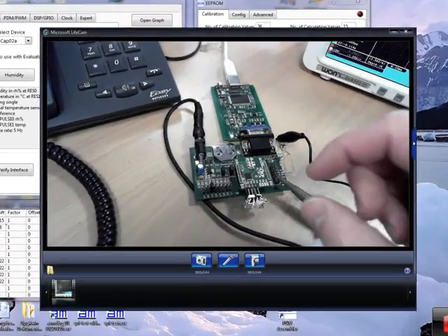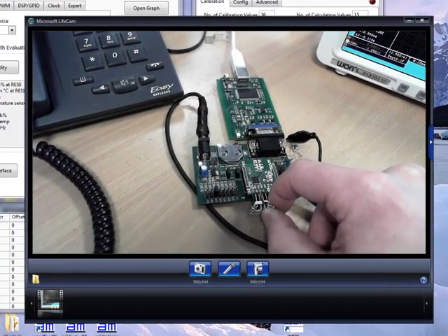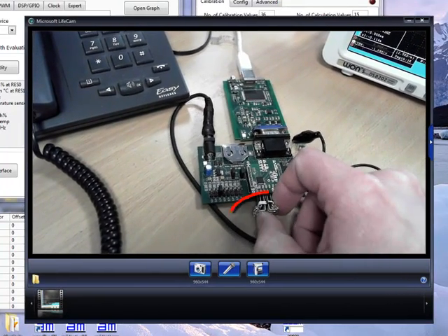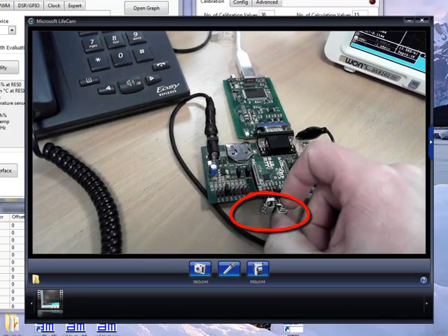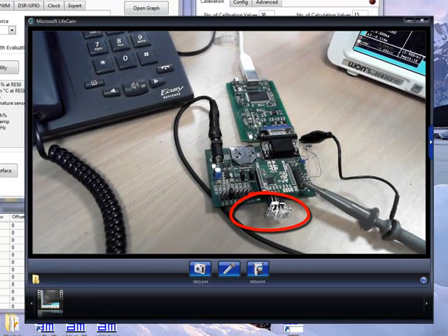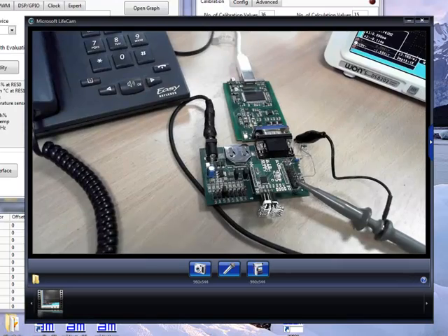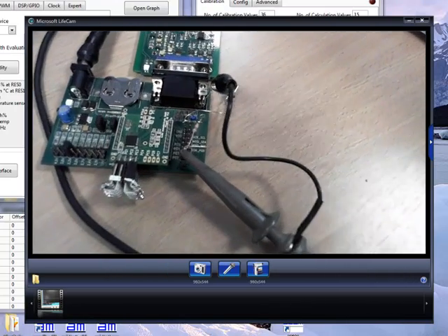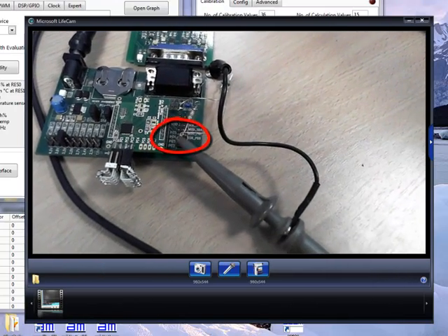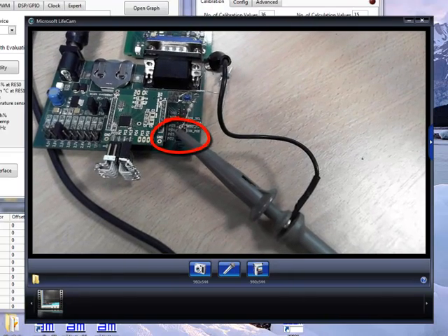I now show you the hardware I have connected to my PC, which is a PCAP02 standard evaluation kit with some fixed ceramic capacitors connected in floating mode from PC0 to PC3, so I can vary them. And I have an oscilloscope probe connected here on PG2 output.